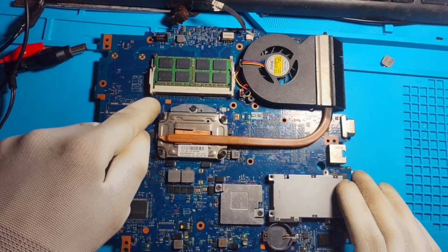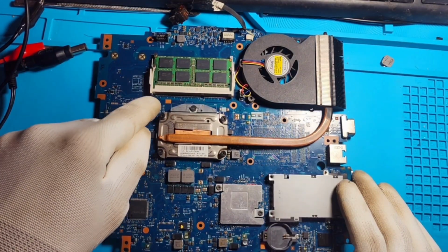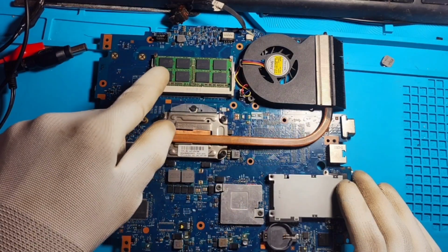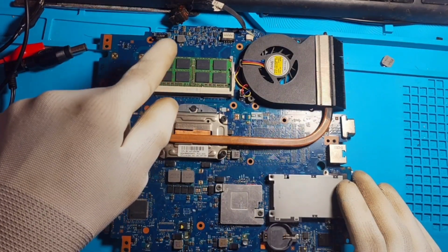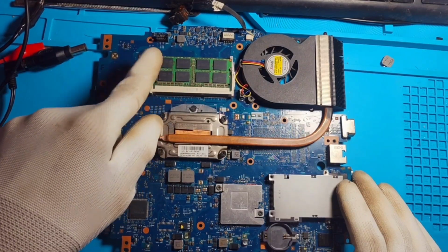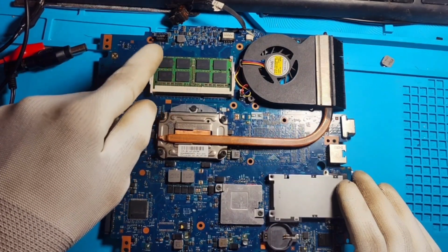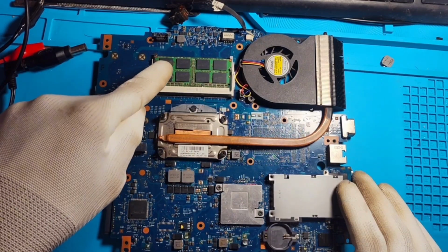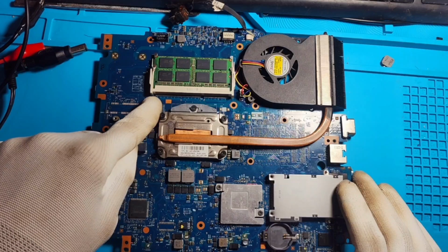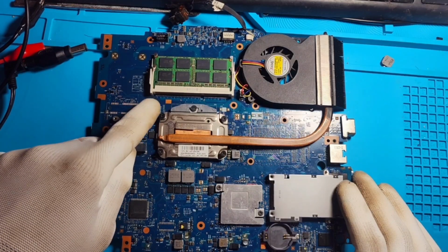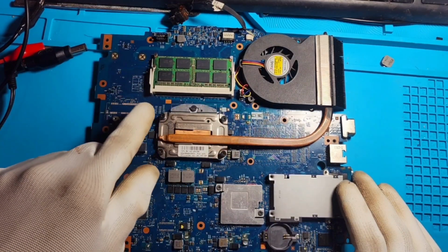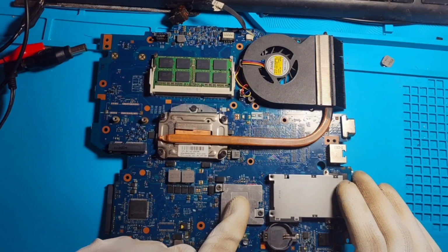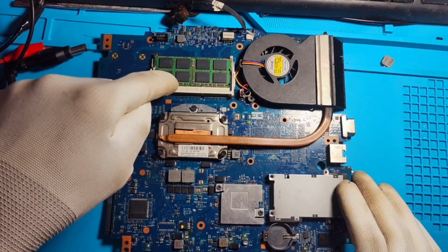So if there is a problem with the communication of the SMBUS line from this point to here, there won't be identification of whether the RAM is connected to the board or not. In that case we will not have a detected RAM and the display will not be executed. Basically we can check this with the multimeter, but for an advanced checkup we have to use the oscilloscope to read the waveform and identify whether there is data going through the SMBUS line for the PCH to detect that the RAM is connected to the board.